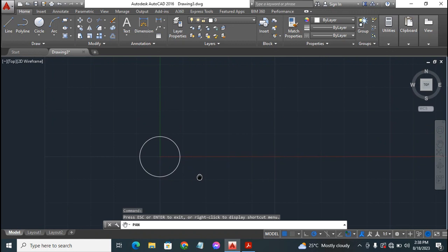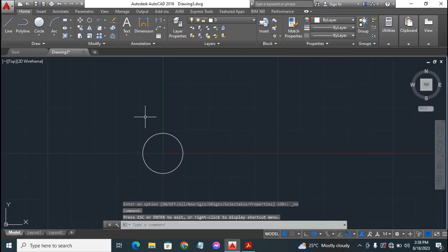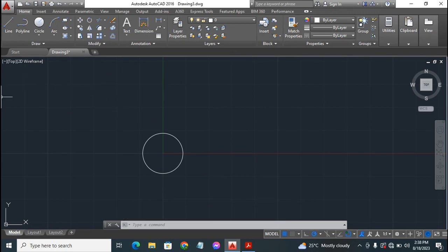I guess this size is okay, so I'll leave it at that. Next up, we are going to draw in a circle that we used to form the second radius we got from our PDF document. Dimension of that circle is going to be of radius 0.750. Okay, so go straight to the draw ribbon, click on the circle tool where my cursor is right now, then come straight to this point.